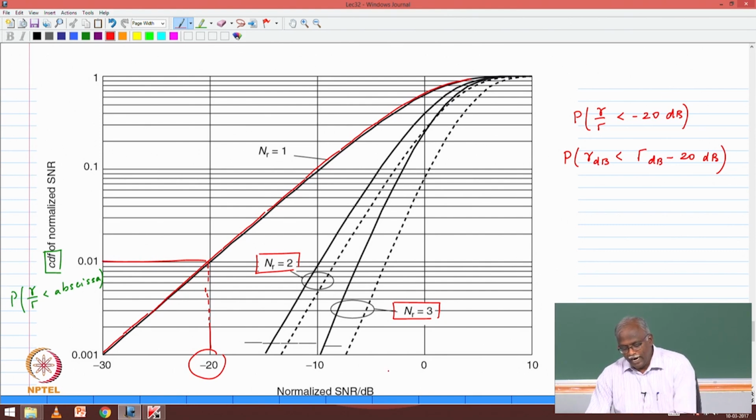And when you take three antennas, it becomes even less probable. So what this is saying is the probability of those bad SNR conditions, which is what causes the fading, is very beneficially removed in the context of selection diversity. So by looking at these CDFs and spending some time with them, you can get a lot of insight into the benefit.